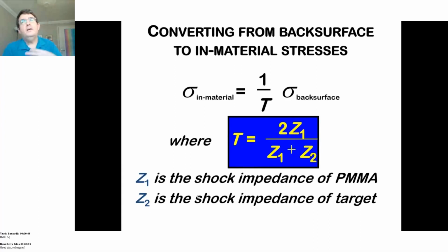So one thing, if you ever talk to me, I can become very insistent and very boring, is use as many useful diagnostics as possible, measure things with respect to time, measure stress, try to measure them independently of one another. That doesn't mean completely different gauges, it means different information extracted from those gauge traces.